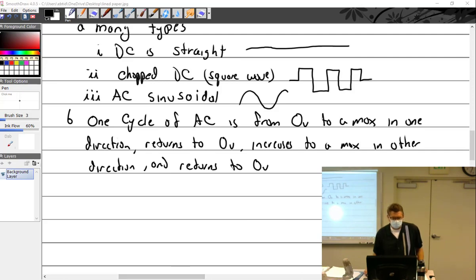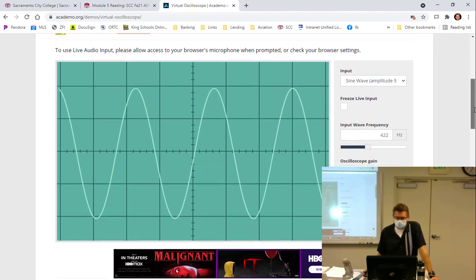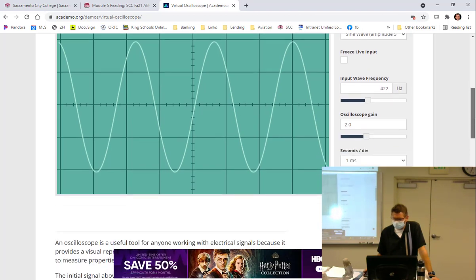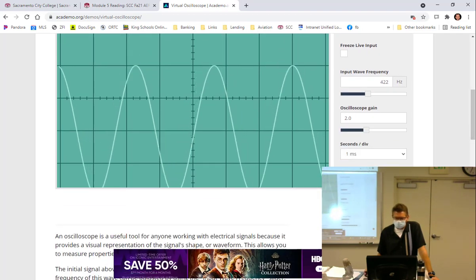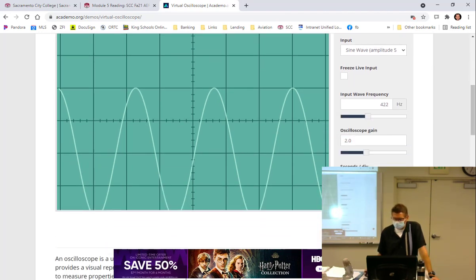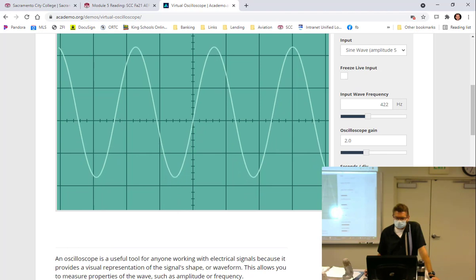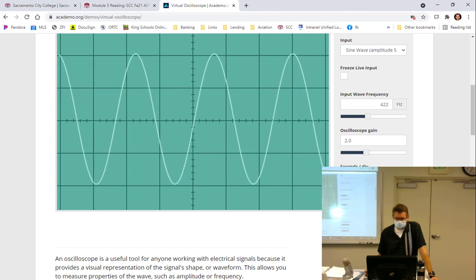So if I go back to this, one of the things I do when I'm working with one of these machines, and I expect you to do because you'll be working with them, is get your waveform balanced out. You want to get it even. If this is my 0 line right here, and I've got most of it down below and some of it up top, that doesn't work. I want to get it right in the middle. There we go. See how it's just touching this line here and just touching that. So I have 2 squares up, 2 squares down.